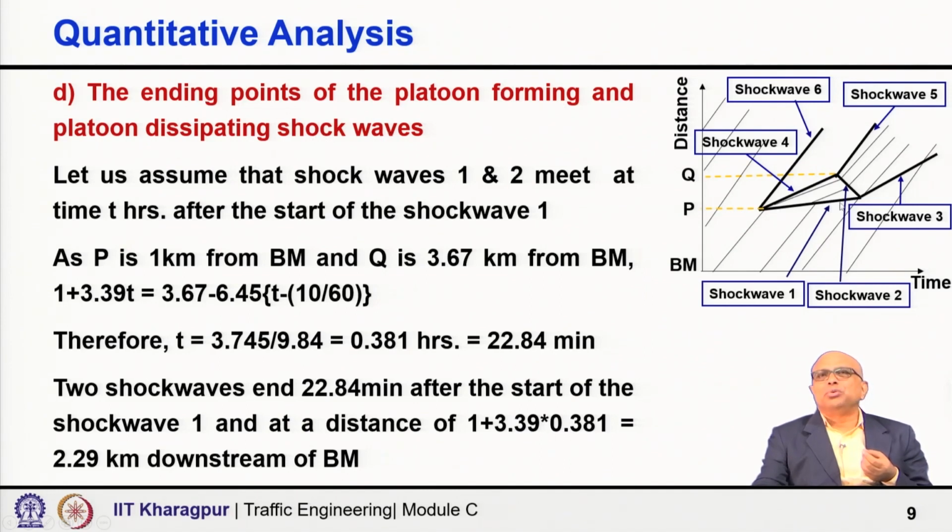Now, next what we want to calculate is the ending point of the platoon forming and platoon dissipating shock waves. When shock wave 1 and shock wave 2 meet, that is the point that we want to find out. Let us assume that shock waves 1 and 2 meet at time t hours after the start of shock wave 1.